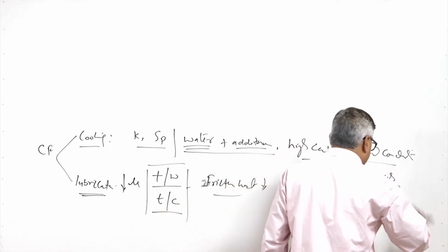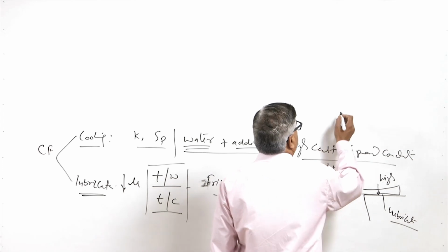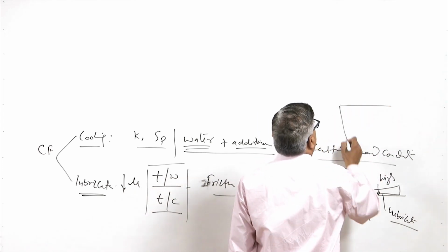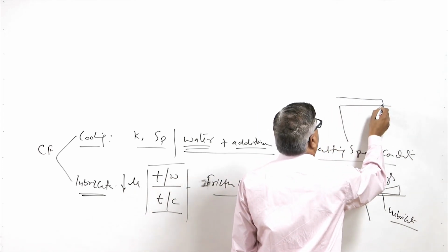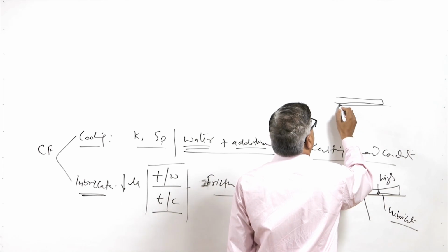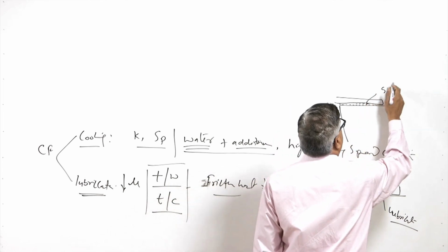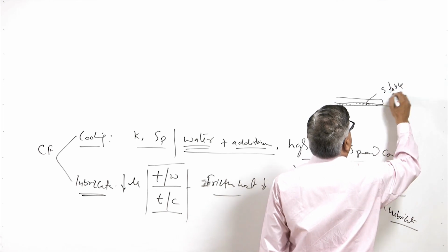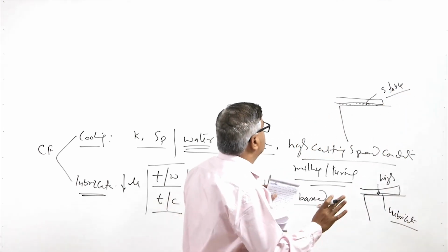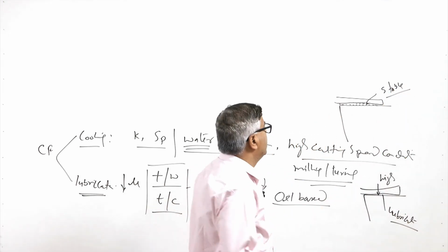So, in order to perform the role of lubrication effectively, the lubricant must be in a position to separate the chip and the tool, and for that it is necessary that the lubricant is stable and does not disintegrate under the cutting conditions of pressure as well as temperature.